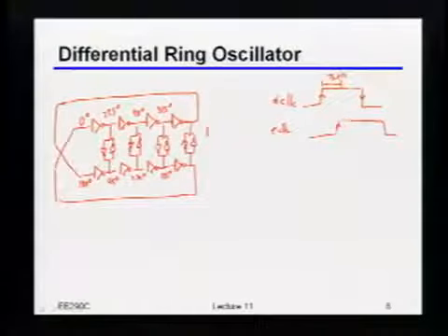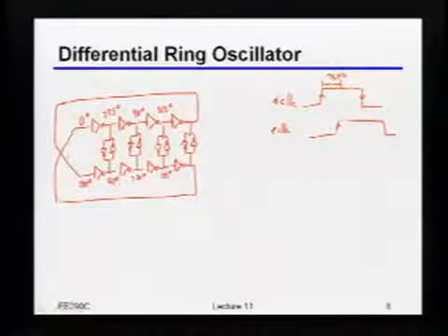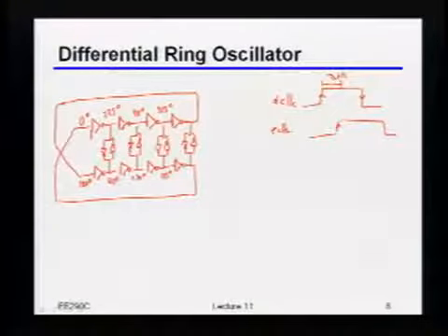If I had a 0 delay inverter, it would be 180. The way I got 45 is that it takes me, to get through this ring, going through this upper path, around here, the lower path, and then back. So there's 8 of them per clock cycle. That's where the 45 comes from. All right, so this is indeed a fairly common technique.